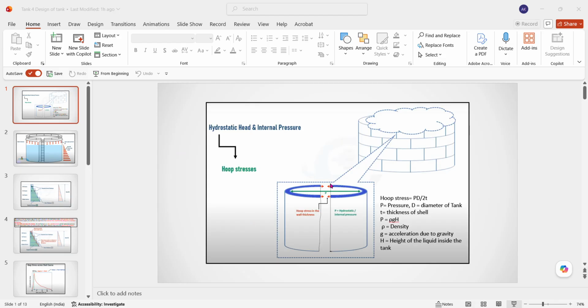Next, the very important thing I am going to tell you is called the 1 foot method, the 1 foot design thickness calculation method. Why are we talking about 1 foot? At 1 foot, the stresses will be maximum. When we come to know that the pressure will be more at the bottom, yes, certainly you are correct.